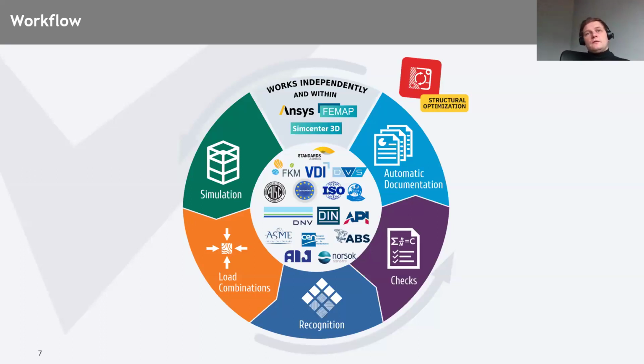It consists of load combinations, taking into account all possible behavior scenarios of the model to run this simulation. It has a detection of structural items, because it's very important within the finite element analysis process. Multiple different checks according to all possible industry rules, not only Eurocode, but much more.